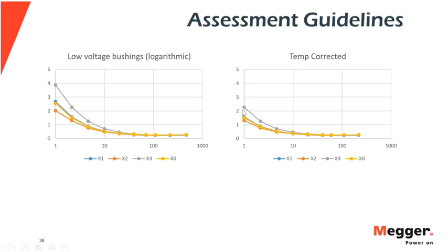But the really interesting information is how at these lower frequencies, where you can pretty readily see the clear separation of X3 as compared to the other low voltage bushings. So that needs to be investigated.